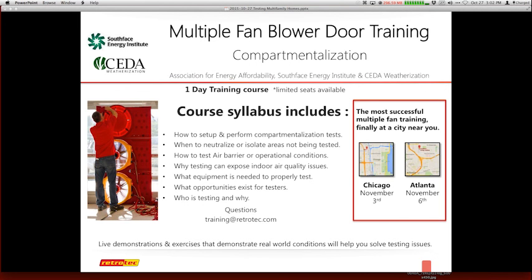But yeah, a few points I wanted to touch on. First one is, when we're talking about air changes, even in large buildings, air changes, even at 50 pascals, is a figure that's useful for looking at ventilation rates and building performance. Whereas flow per unit area, which is typical of the U.S. Army Corps spec and so on, is really a measurement of how well the enclosure itself is constructed from an air tightness standpoint, or how well the air barrier is constructed. So they have different purposes. One is performance of the building in real life, so to speak, and the other is the performance of the air barrier itself.